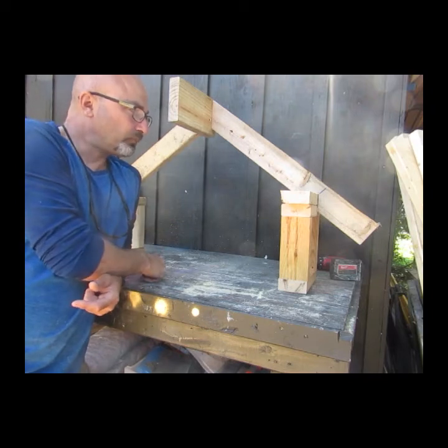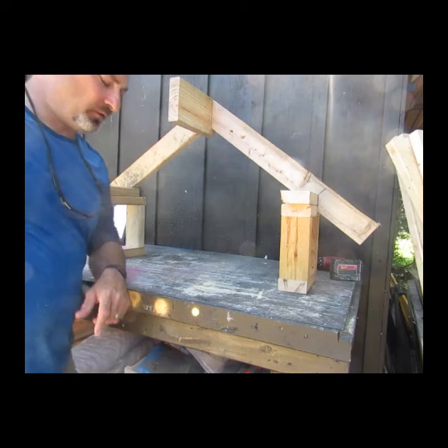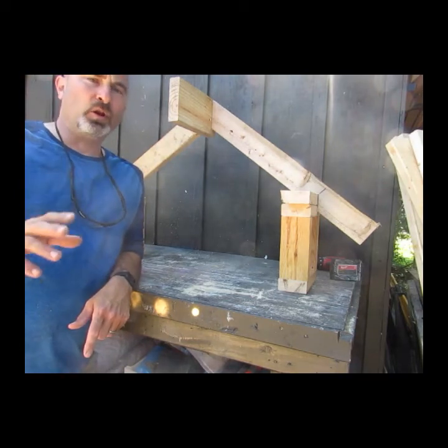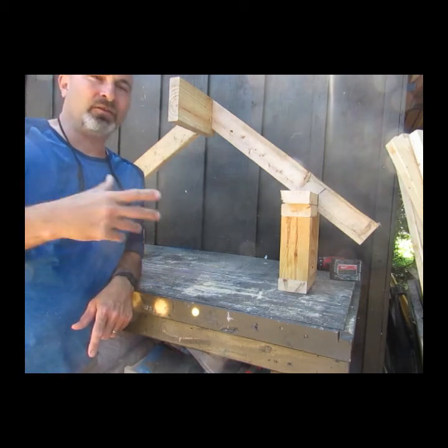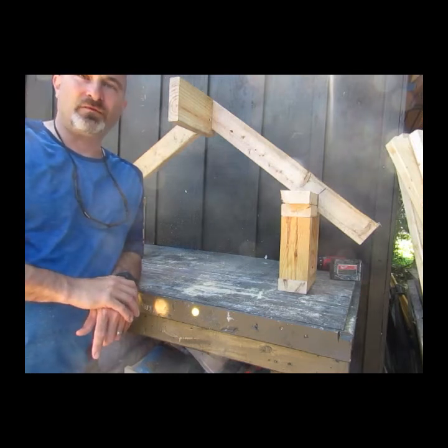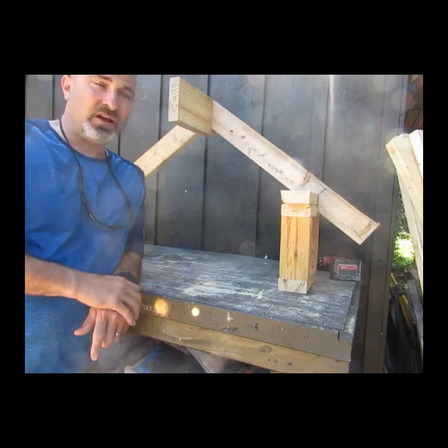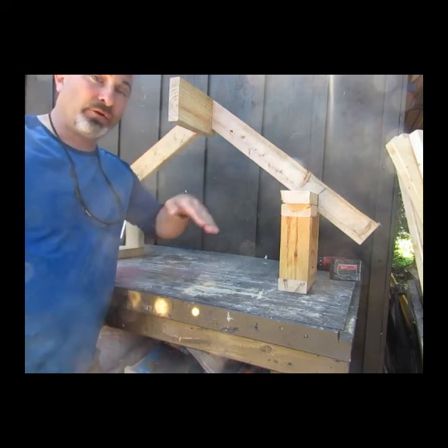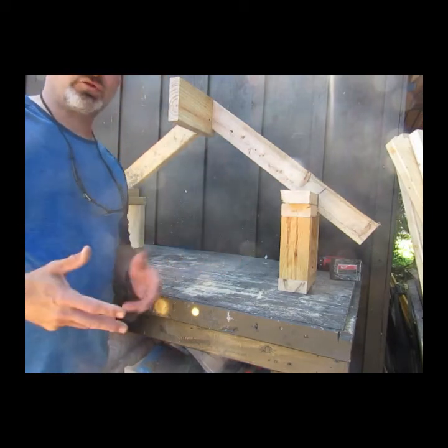So the nail, much like we talked about earlier in another video, in order to counteract the four forces that are constantly trying to pull and push your structure apart, you need to place the wood in the right orientation. The fasteners, the nails, aren't designed to stop the house from falling down. The nails and all of the mechanical fasteners are there to hold the wood in place so that their correct orientation and application will resist the forces trying to push and pull it.